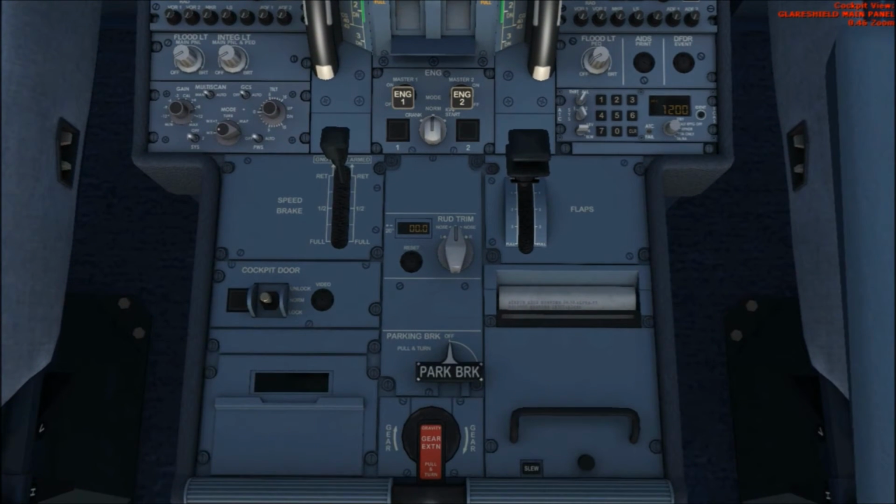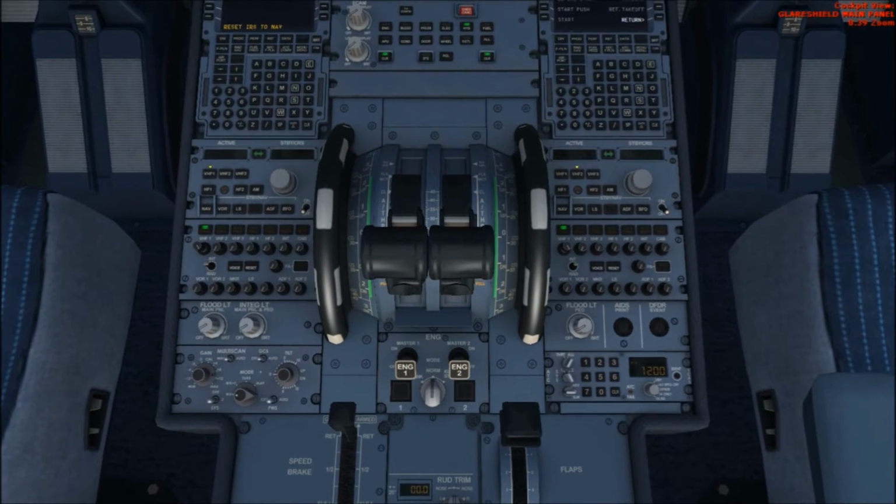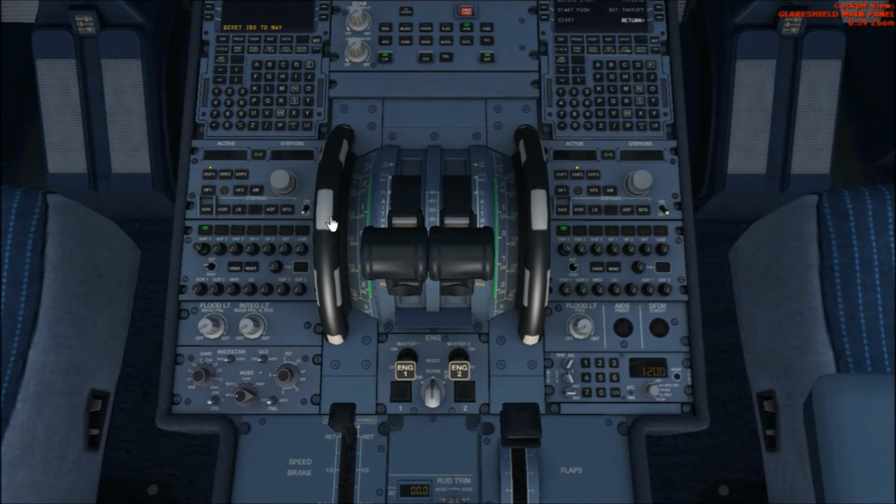Now, for the past few items on the checklist, the Copilot's been asking the state of things. We didn't have to press anything because she's just asking what state they are in. The pilot's saying check, it's up, the flaps are up, the speed brake's up. We didn't have to do anything. She has asked now for the radio panel to go on. We have to do that. Both that switch and that switch will turn it on. I'm going to use the right switch, just left click it, and it will turn the radio panel on.